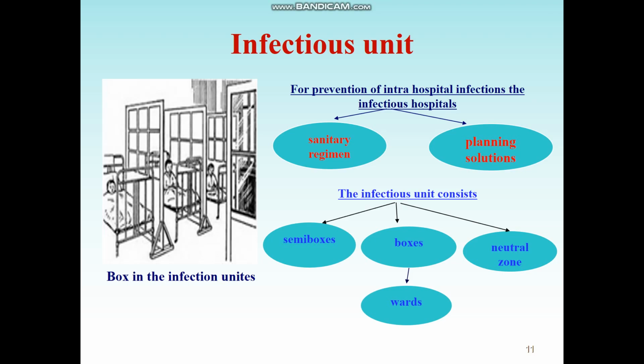The box is the most reliable isolated ward to prevent intra-hospital infection. It consists of a complex of premises: entrance tambour, lavatory with a bathroom, ward, and sluice with a separate external entrance. The sluice uses the box with a central corridor, and this corridor is for the personnel to enter the patient. There are a washstand, coat rack for doctor's smocks, and built-in cupboard for food delivery in a sluice.